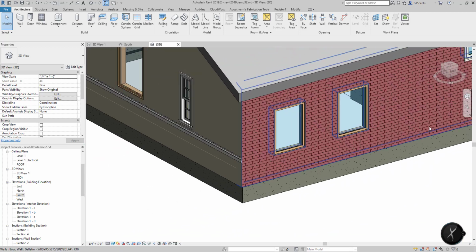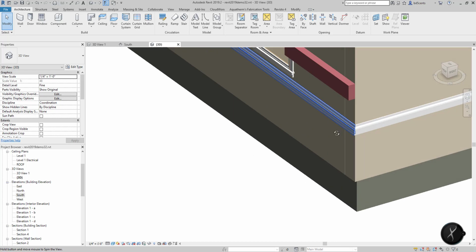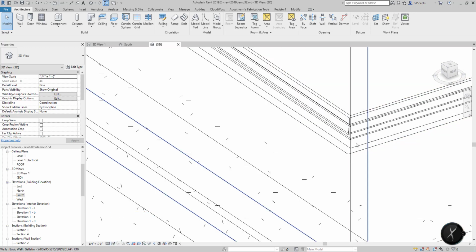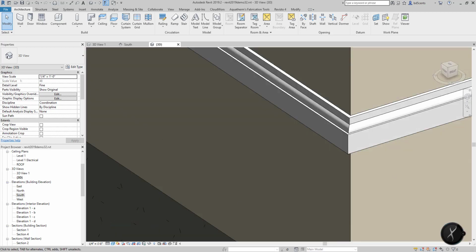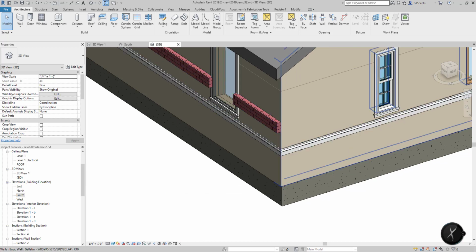So if I rotate around onto this side, that cut mark's still in there. And it's still in there as well. Now, if I truly wanted to see that, I could adjust my shading to be a wireframe, and I could see that there's an interior cut in there. But we'll go ahead and leave it on shaded for now, and we'll continue along. Now, you can do an align tool to basically join them, and that's essentially what we did.